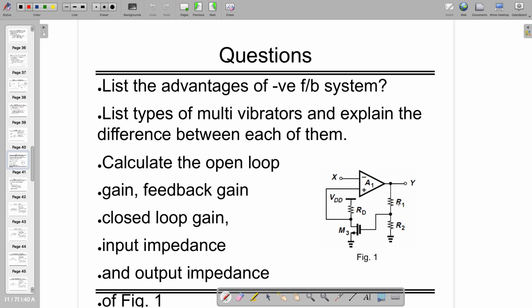For the same thing, let's say you have such a network where this is minus and this is plus. If I increase this, notably this is the plus terminal, so this has to decrease. If this decreases, this will decrease. If this decreases, as this is common source, it's also going positive. So then it becomes positive feedback, so this has to be the minus terminal. Then this is going down. Okay, I made a mistake. If this is the plus terminal, this is going up, this is going up, this is also going up, this is going up means this is going down. Yeah, so this entire loop is negative feedback. When it comes back, you have to make sure that negative feedback is in the reverse direction of this one so that it becomes negative feedback. So right now it's negative feedback.